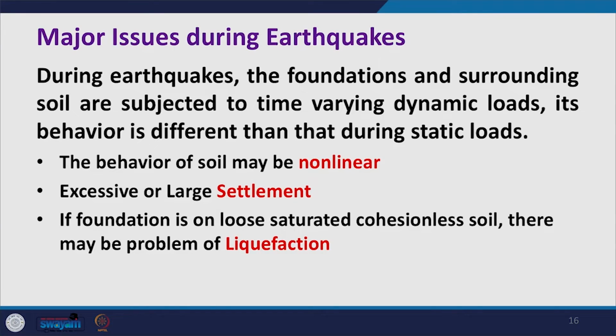And if the foundation is on loose saturated cohesionless soils, then there may be a possibility of liquefaction, which also needs to be accounted for. So, while dealing with earthquakes, we need to take into account all these issues.